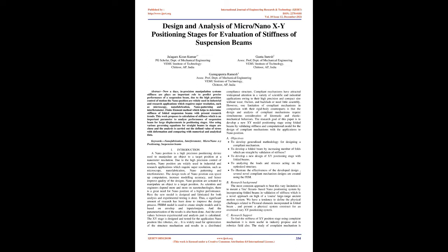This work proposes the calculation of stiffness, which is an important parameter to analyze performance of suspension beam for large displacements in positioning stages. Also, using various governing equations for straight beams, stages are chosen, and the analysis is carried out with the defined value of stress with deformation and comparing with numerical and analytical data. Keywords: nanofabrication, interferometer, micro/nano XY positioning, suspension beams.